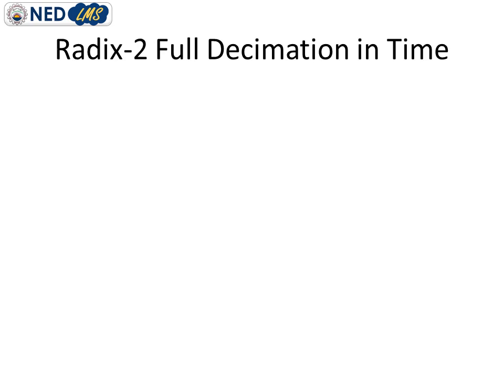If we have 8 samples, then we first divide those samples into 4 samples, then the 4 again divided into 2 samples, then those 2 will further divide into 1 single sample. So we decimate the original signal completely. That's why this is known as the radix 2 full decimation in time algorithm.